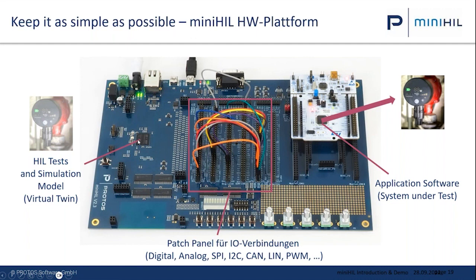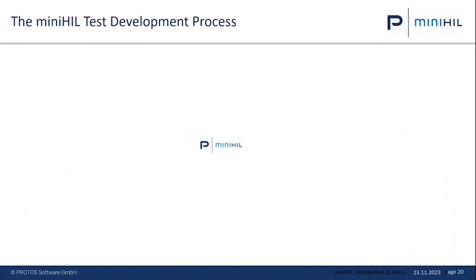So in our test system, you now need three things. First of all, you need access to the pins of the microcontroller you want to test. So you need to control the I/O. Then on the second level, you need to simulate motors, temperatures, batteries, and so on, because your microcontroller or your application fails immediately if no simulations are attached, or if no real hardware is attached. So that's why we simulate all the I/Os. And the third level is, on top of that, now you can build test cases for the happy path and for the unhappy paths. How do we do that?